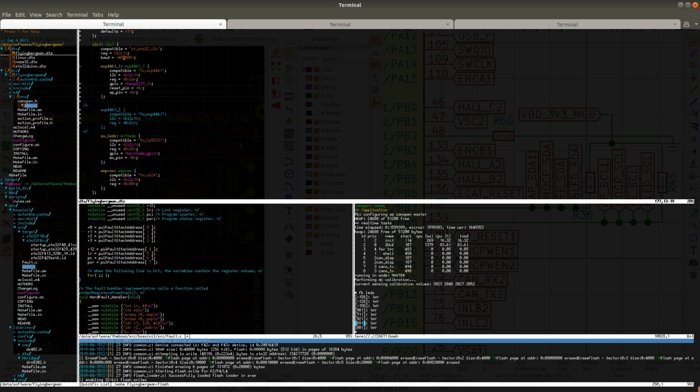I mean, it could also be that using this baud rate with my current clock is actually giving much better precision for the data somehow. But it shouldn't even matter because I2C is using its own clock. But I don't know. Maybe there is some interference, or maybe this read operation is happening so fast that it either fails completely or completes completely. Maybe the problem will show up again. For now, I can use this to do further testing, but this is definitely something to look into.